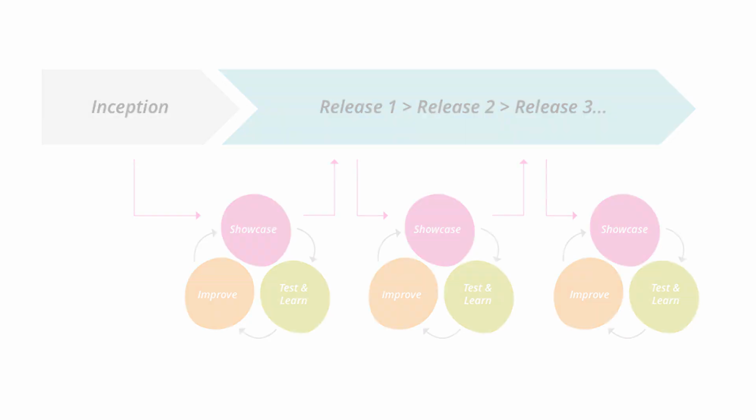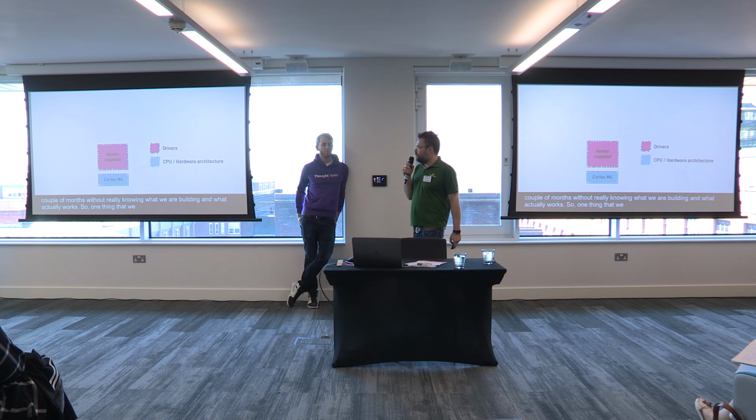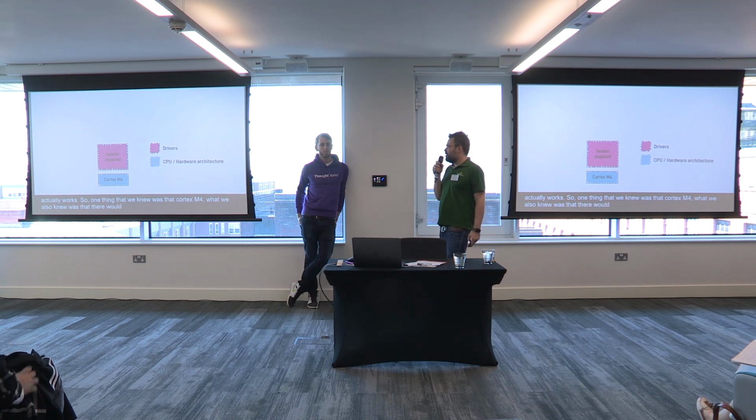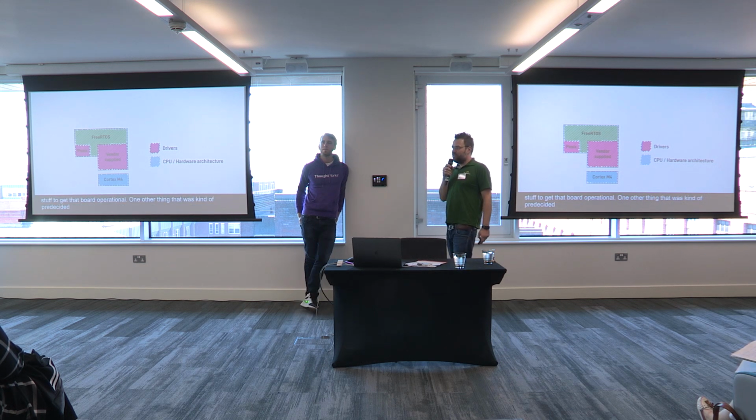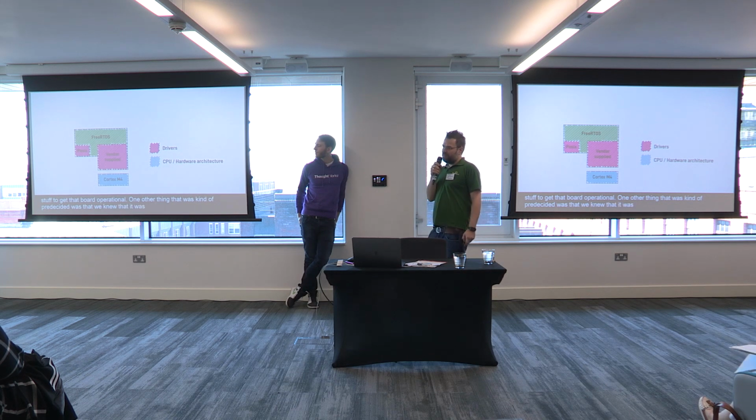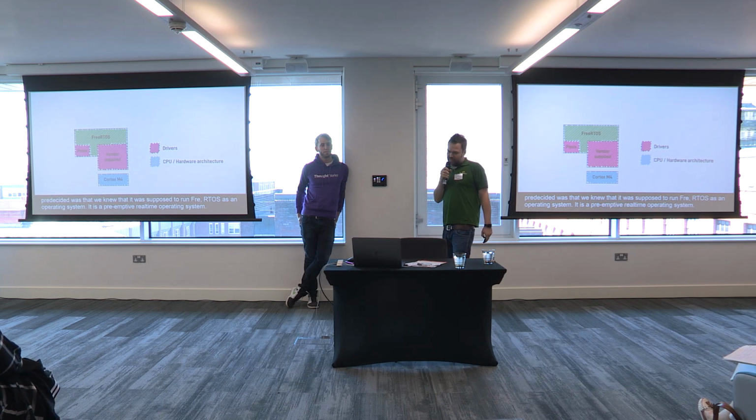One thing that we knew was the Cortex-M4. What we also knew from the specs is there will be some vendor-supplied drivers and all that stuff to actually get that board operational. One other thing that was pre-decided was that it was supposed to run FreeRTOS as an operating system. This is a preemptive, more or less real-time operating system. And what we wondered is, okay, we have our development machines, we have no hardware yet.